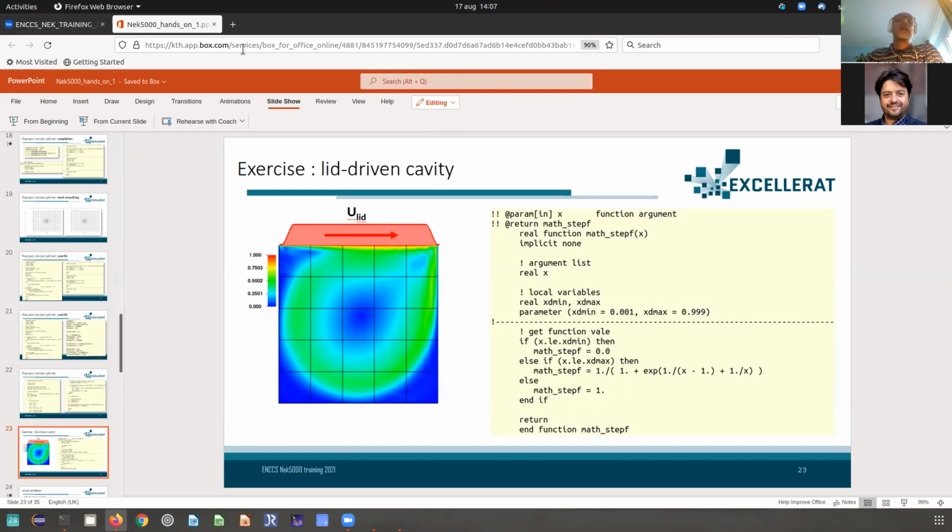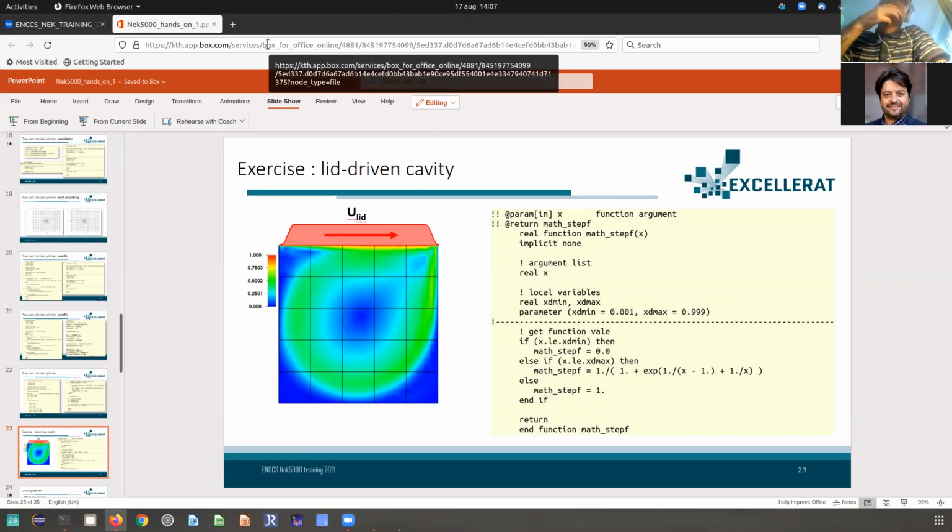Yeah, you can have the time-dependent boundary condition. User BC is the routine which is called during every time step. So if you have time-dependent boundary conditions defined there, then they are time-dependent. What do you like, sinusoidal inlets or something like having an edge as an inlet for some time and the outlet? Changing inlet and outlet I never tried, and I'm not sure it would work.